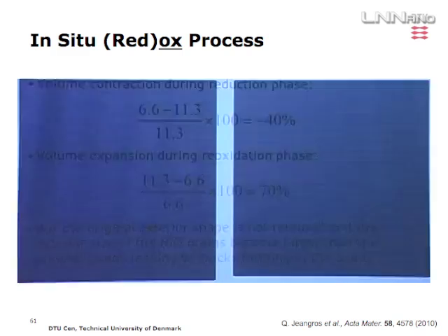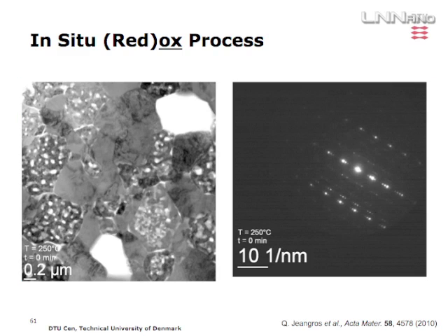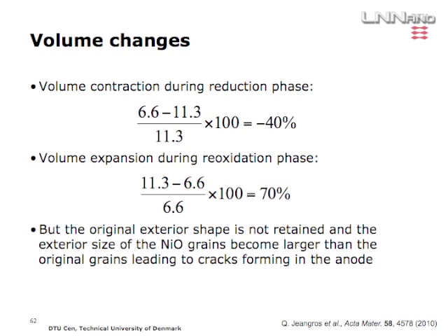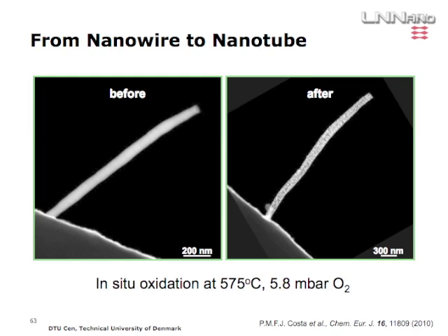And when you have a polycrystal, it takes up more room than if you have a single crystal, because there are going to be little gaps and holes in it. So that's detrimental for your fuel cell, because all of a sudden then the nickel oxide grains take up more space, and your whole system cracks together because the volume becomes too large.